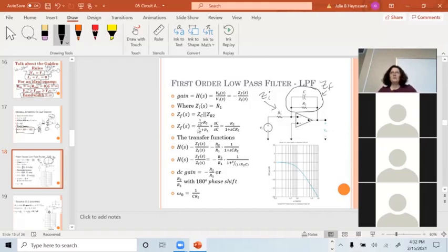And you always put the feedback network on the negative input. If you make the mistake and flip the terminals, what you've done is you've just created a positive feedback amplifier, which by its nature is unstable. You've built an oscillator by flipping those two terminals. So be careful with that one thing. That's important. Okay, so I've got a formula here for the gain.